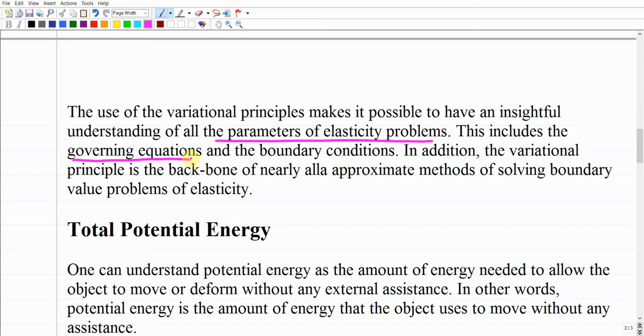We said that in some special structures like beams and plates, it is recommended that we reformulate the equilibrium equation in a form that shows the bending moment instead of just the stress. The stress and bending moment are both stresses, by the way, but they are different forms of the stress. So we need the form that shows the bending moment. This is much more convenient and consistent with beam and plate structures. In the Newtonian method, we have to make changes that mainly depend on our understanding.